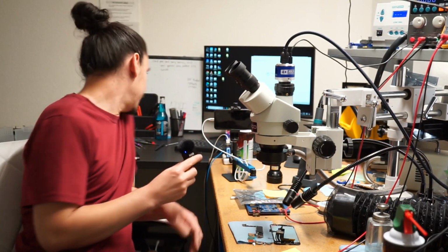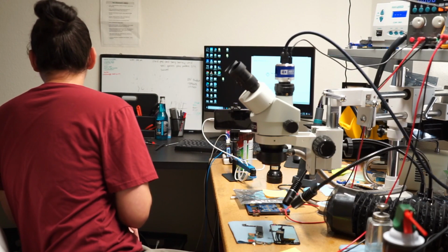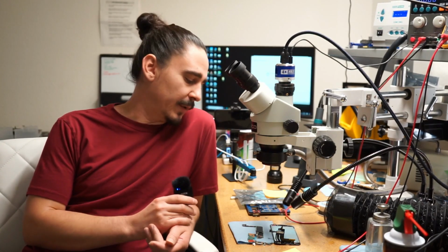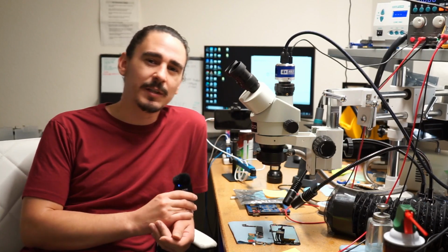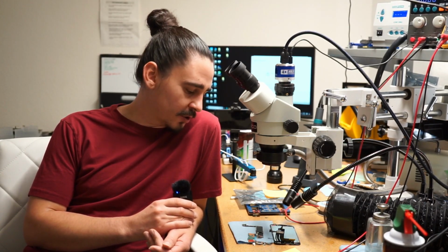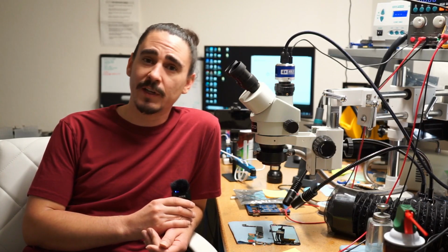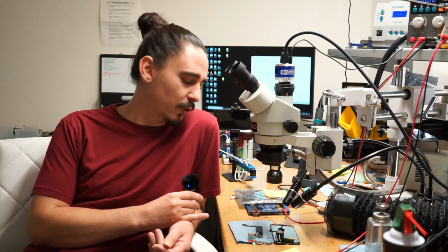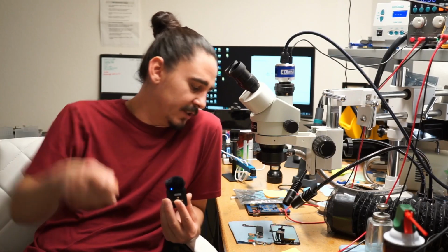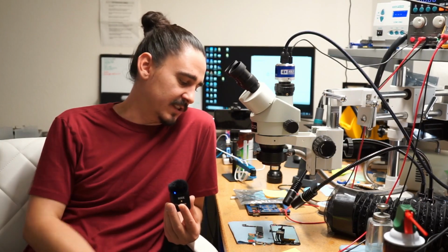And it had signs of work on that board. So that battery looks all mangled. So it's definitely been opened. So she took it somewhere, and that technician put the wrong screw in the wrong screw hole, and it caused a line on this board to become shorted to ground by like digging that screw into the motherboard and pushing those traces down a little bit.